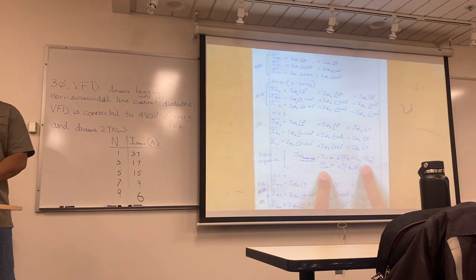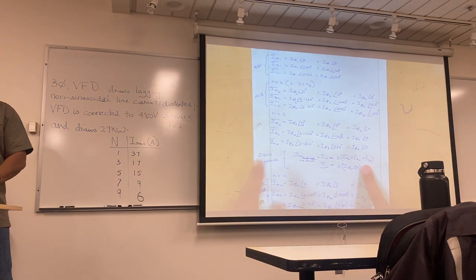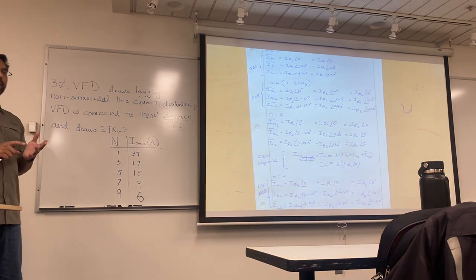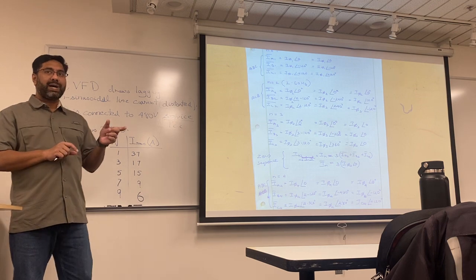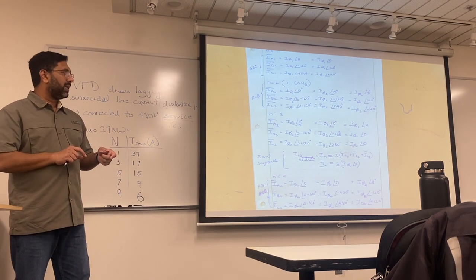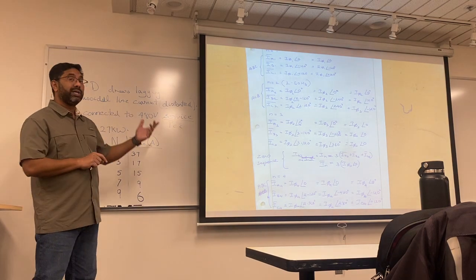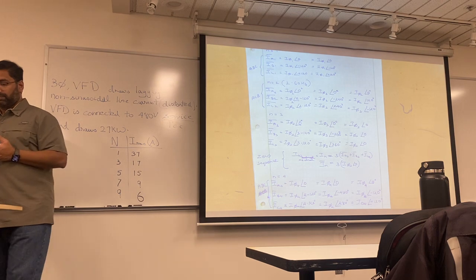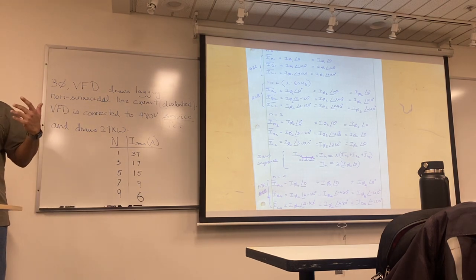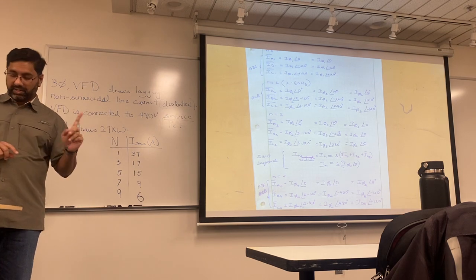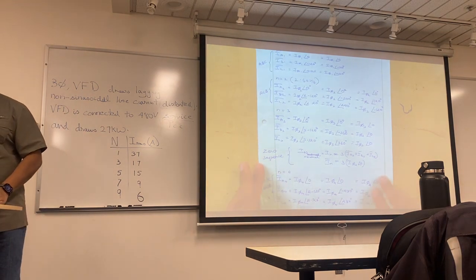Just going to jump ahead and just tell it to you guys. Because this is a frequency, the easiest way is what you have seen in your 200 level. Make a bandpass filter or some sort of a filter that will just take out multiples of, will take out the triplets, so to say. So you come up with a filter that takes care of the triplets. Triplets if it is a 3-phase, not 2-phase. Again, I'm going to repeat that.